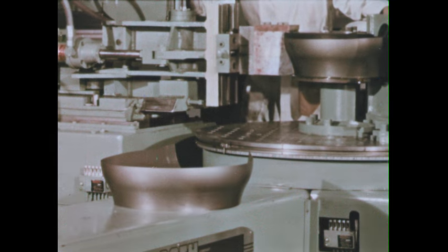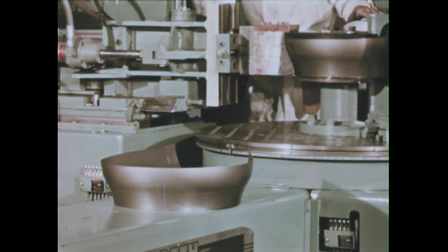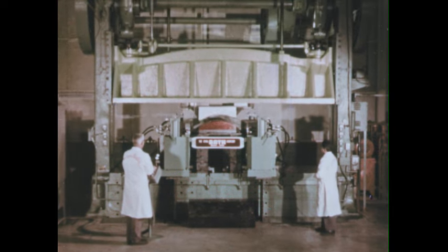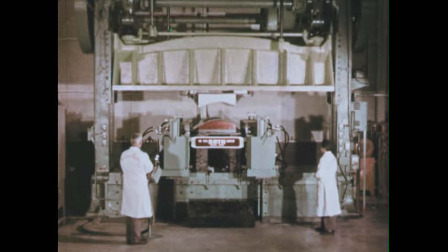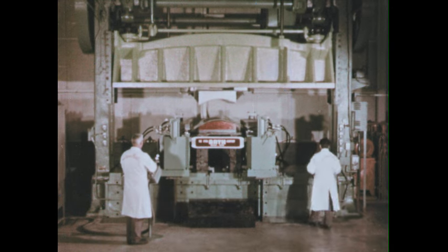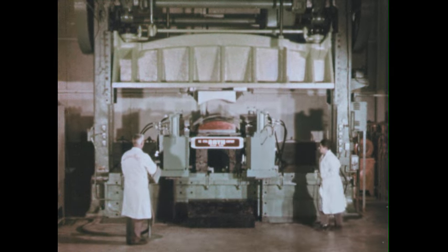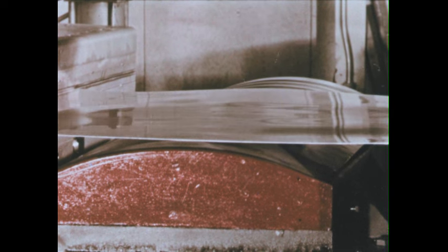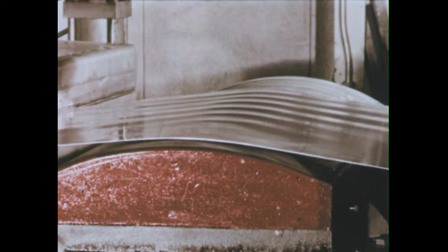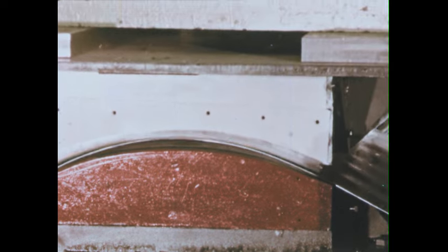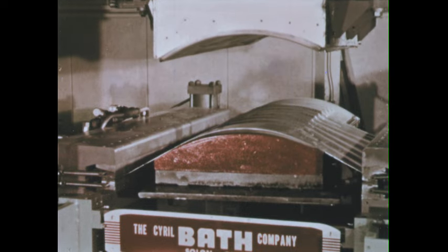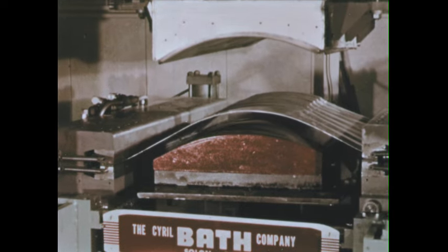And the savings over conventional methods is 80%. A similar type of process will give you savings of up to 90% on drawn components like this, and permits the use of inexpensive dies. This blank holder, adapted to a conventional press, pre-stresses the metal and makes it more flowable than plastic. By adjusting the stress, almost any metal can be formed using the same die.